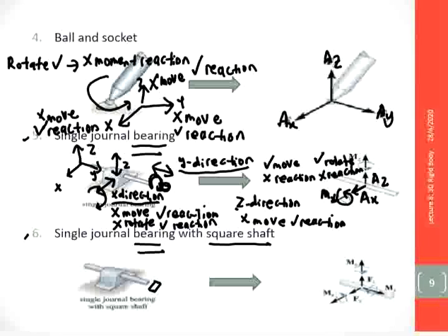And for the z direction, z is upward, this shaft cannot rotate about the z axis, so there is a moment reaction, Mz here.